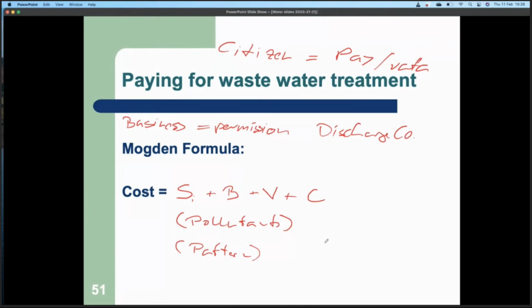So I mentioned breweries before, or any other processes where you have batch operation. So if you produce a lot of water at a certain time and release that all at the one time, then you will have a very high volume all of a sudden, very high BOD loads, solid loads, pollutants loads, and so on, that might temporarily overwhelm the treatment works.